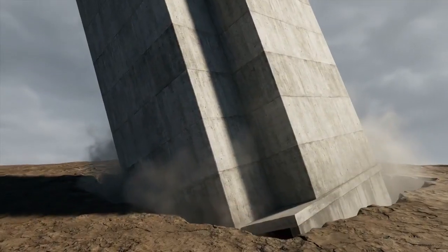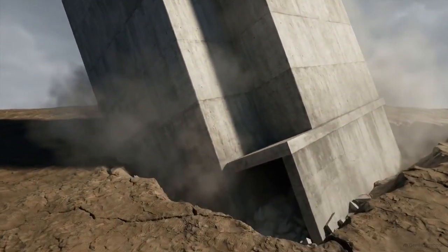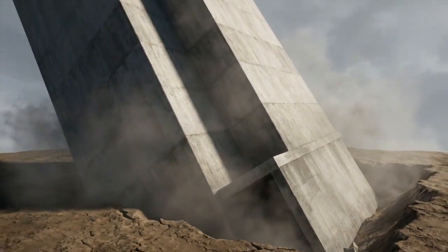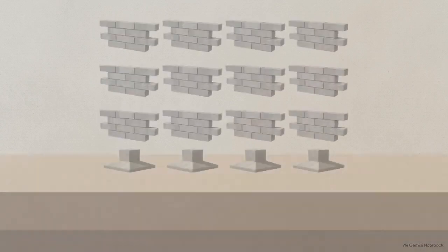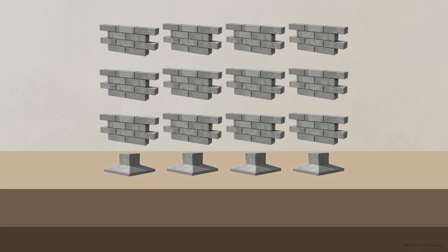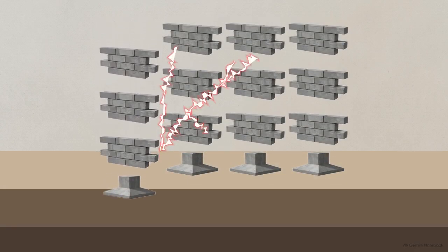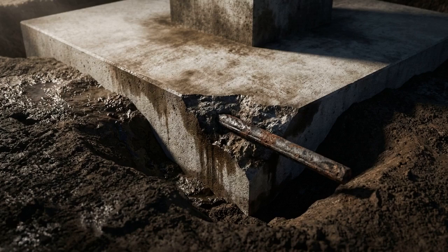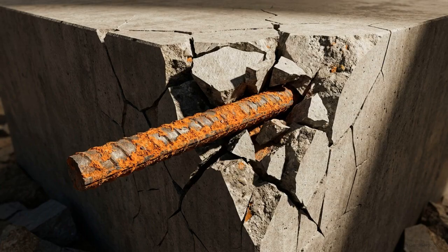When a foundation fails to spread its load properly, usually due to poor soil checks or incorrect footing sizes, the building experiences differential settlement. This elevation shows the results of that failure. One corner of the building sinks deeper than the rest, triggering a cascade of stress fractures that rip through the walls. Internal execution failures are just as destructive. Poor compaction causes honeycombing, and inadequate concrete cover allows groundwater to reach the steel. The rebar rusts, expands, and destroys the foundation from the inside out.